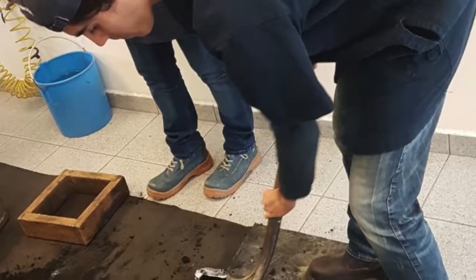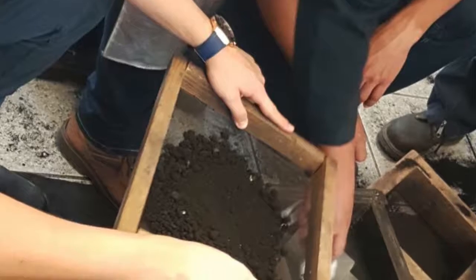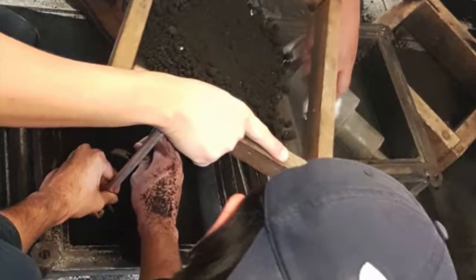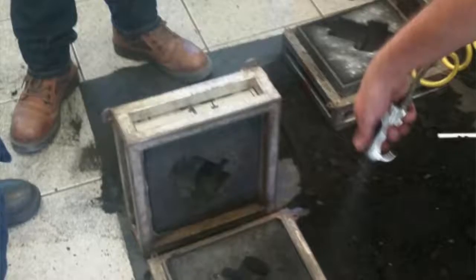For the process, we first threw sand on the floor with water and bentonite and broke apart all the lumps of the sand. Then we prepared the mold A on the sandbox, putting some lime powder, and then we sieved the sand into the sandbox with the half of the mold inside. After that, we put pressure on the sand so it wouldn't fall when it was lifted. We repeated the process for the side B of the mold, and then we took the mold out of the sand.